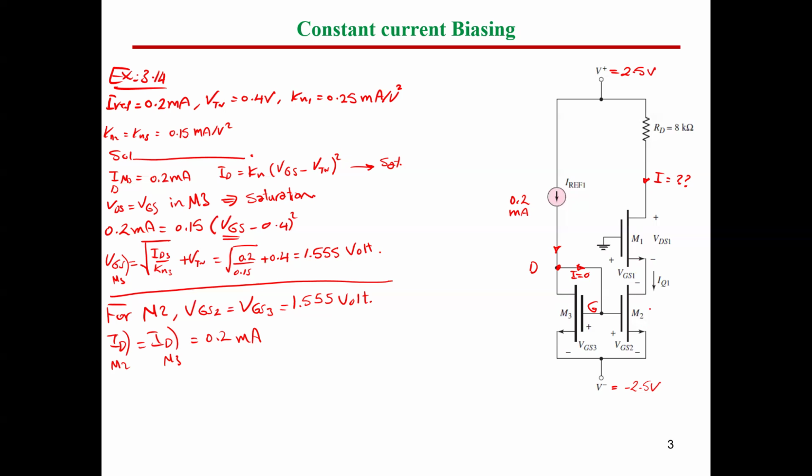So we can say now, if we have a branch of MOSFET like that, connected to a drive MOSFET like that, sorry, a load MOSFET like that, by connecting the gate to drain, the current flowing in the load MOSFET will be the same as the current flowing in the other MOSFET. Okay.